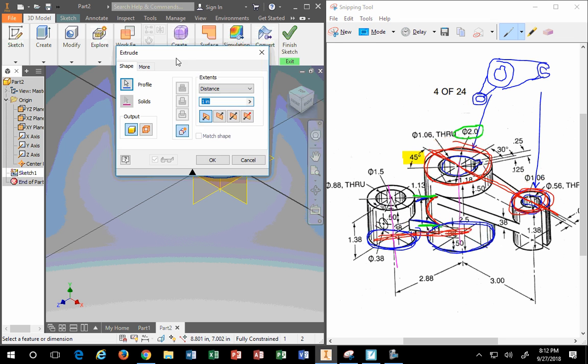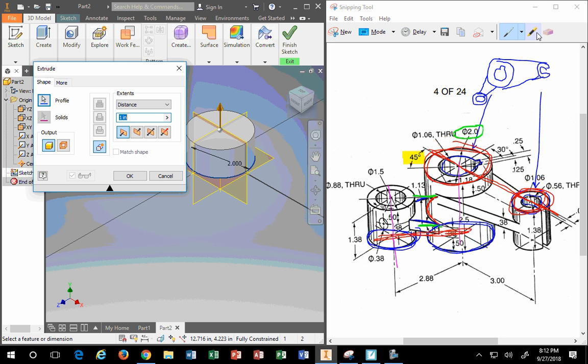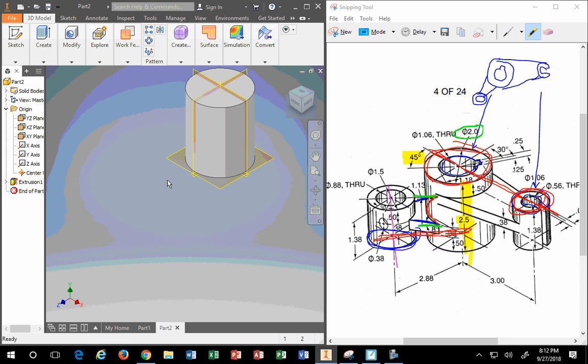The height that I want to extrude is the height of the object, which is given here. And that height, let me highlight it right there, is 2.5. That is this vertical height of this object. This vertical height. So that's what I'm going to type in here, 2.5, and done. Now I basically have the top of my object and the bottom of my object.